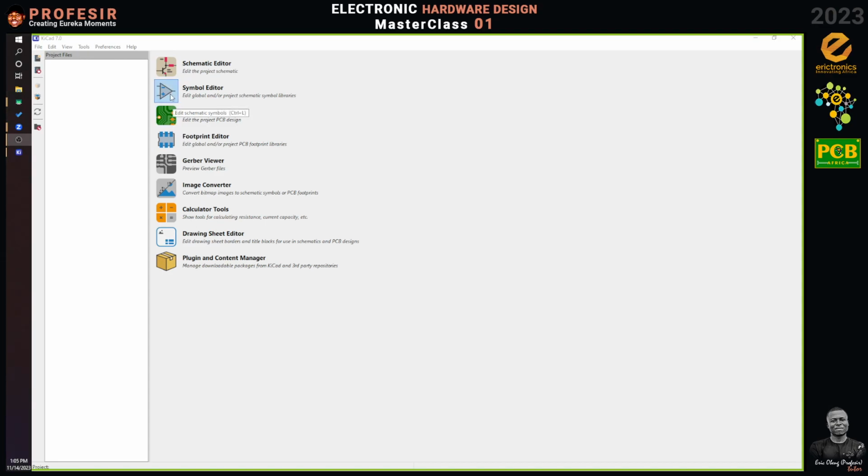What we call symbols, what you call circuit symbols, we use in schematics. But when you come to the PCB, we call those things footprints. A footprint is the physical design of the component, its pin mappings, and all that. Is that okay? Good. So again, this tool is used to manage and also design your footprints.